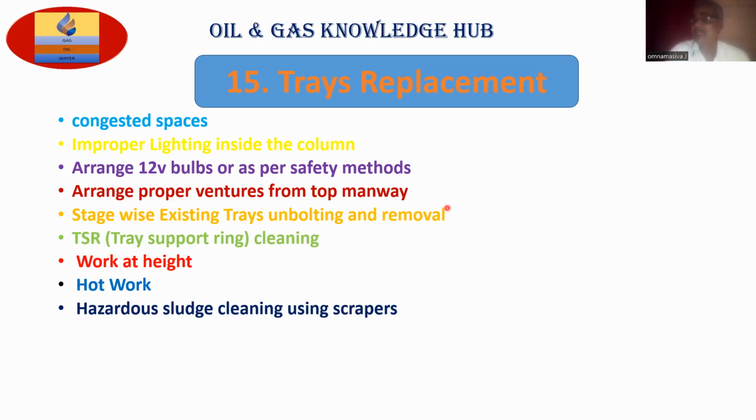This is a fractionation column. The process media is crude in the form of vapors at high temperatures and high pressures, and condensation also will be there. If it is sour service, that means hydrogen sulfide service, then you will find hazardous sludge, called pyrophoric material. That should be cleaned properly.